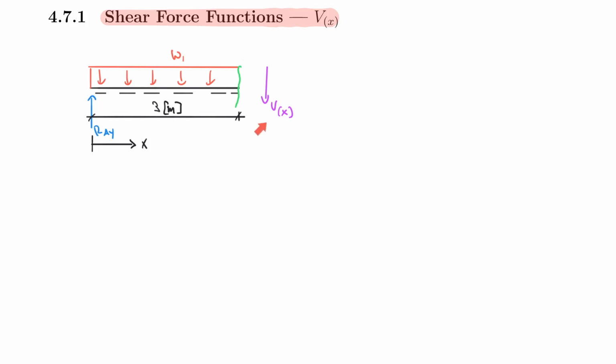And the way I can calculate the shear force as a function of x is very simple compared to what we know already, because we have done it many times before just with a finite number here. All I have to do now is replace this 3 with an x. So let me erase those parts as well. I'm not going to think of x as 3 meters. I think of x as a variable, and this might be in meters or any length unit really, and then it grows in this direction.